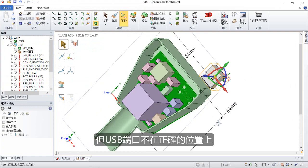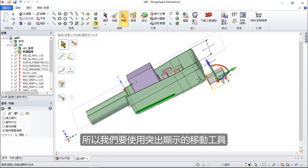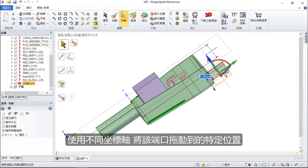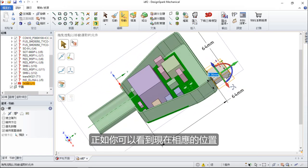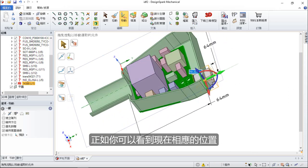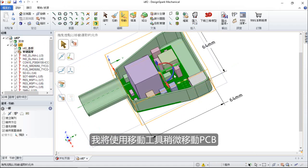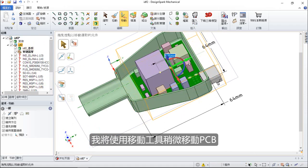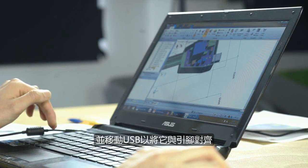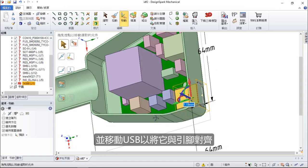This currently is not in the correct position, so we can use the move tool, which is highlighted, to drag this item into position using the different axes. As you can see, you can position this accordingly. I'm going to have to move my PCB slightly using the move tool as well. And then again move the USB just to line it up with the pins.